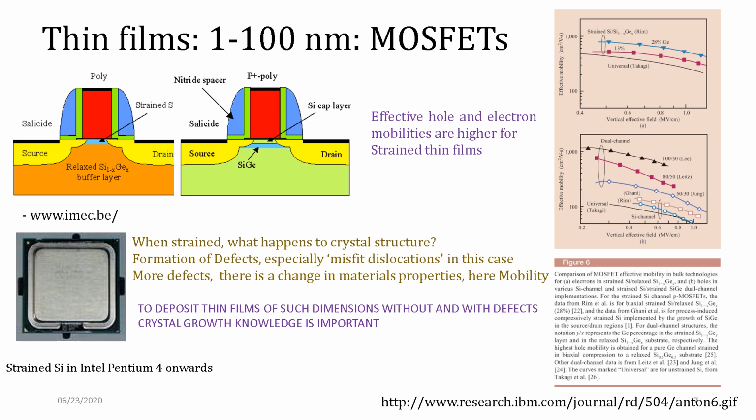This is because when the crystal is strained, or when the lattice is stretched out, we can have defects which can kill the property, or sometimes it can enhance the property. So for this reason we need to know a little about materials and more about material deposition, materials growth, which is also a part of fabrication.